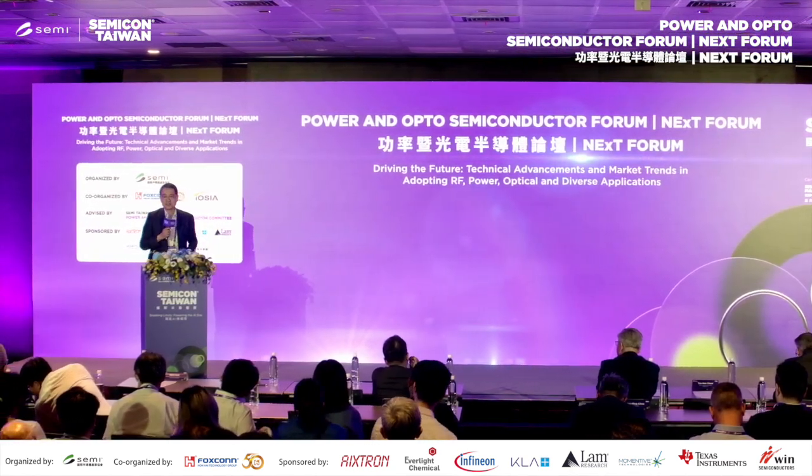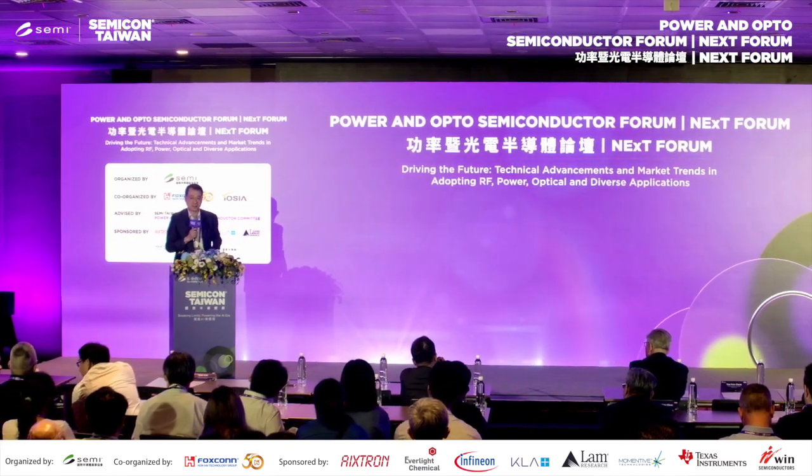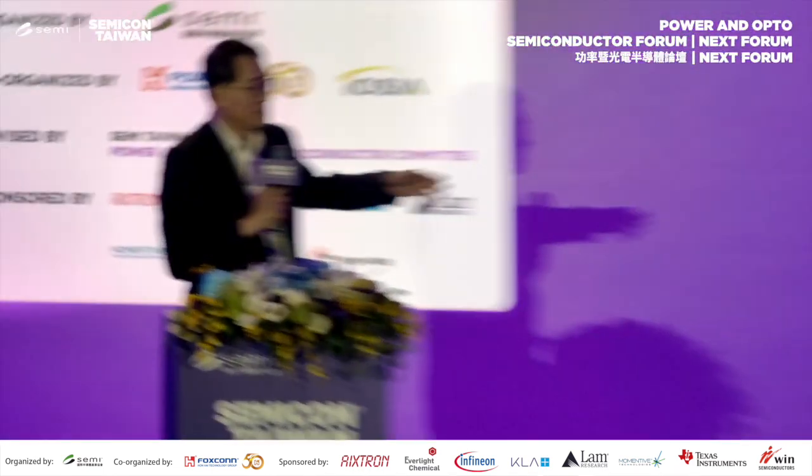Yes, that's everything from the material quality, because this is heteroepitaxial growth. There exists a 6% lattice mismatch. Although gallium nitride can have perfect crystallinity after the interface engineering, for the oxide semiconductor the epitaxial growth mechanism is not very clear, because it's totally different from the III-V material.